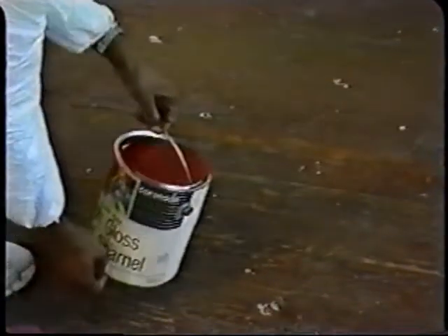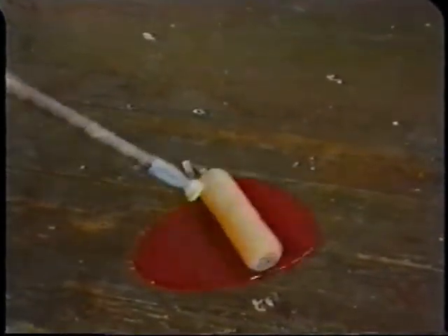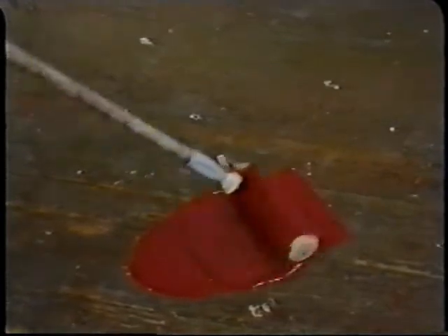Before clearance, all treated surfaces should be sealed so that their surfaces are smooth and cleanable. For example, newly replaced woodwork and repaired wall and ceiling surfaces should be primed and repainted. For best results on problem areas such as window sills and wells, a finish coat of enamel is recommended. Wooden floors should be either sealed with a deck enamel if previously painted, or a clear urethane sealant if not painted.